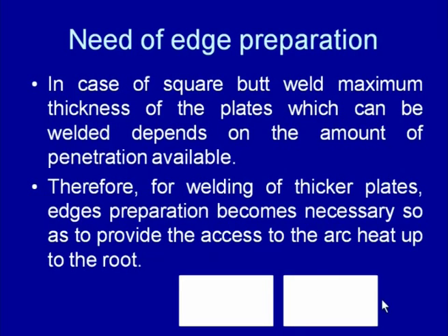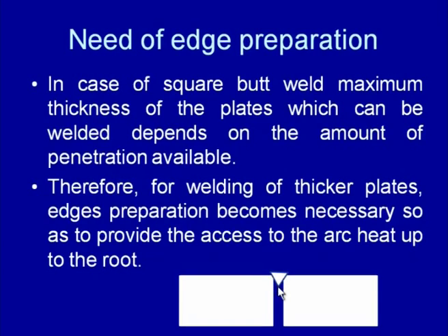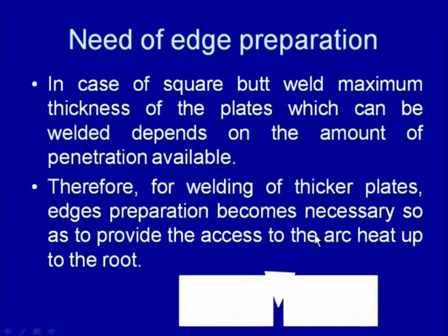Application of heat from the top will be less effective; if the heat is very little, then only the near-surface edges will melt. If we increase the heat input, then the depth up to which melting takes place will increase. So if we require greater depth of penetration, the heat input has to be increased, but there is a limit on the extent to which heat input can be increased by a given process.